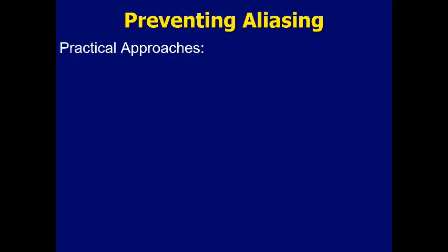Let's pick up on our discussion about what do we do to make sure aliasing doesn't happen in our discrete time sampling systems. Last time we introduced the idea of including an anti-aliasing filter, an actual hardware low-pass filter in front of our A to D conversion hardware, so that even if our signal coming into our system had frequencies that could potentially alias, that filter would try to remove them so that after the sampling process, we didn't have any aliasing involved. Now, that is a wonderful concept.